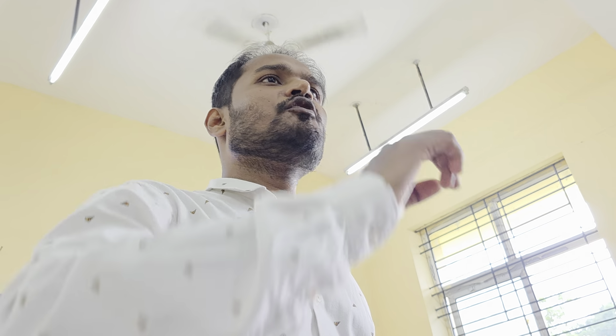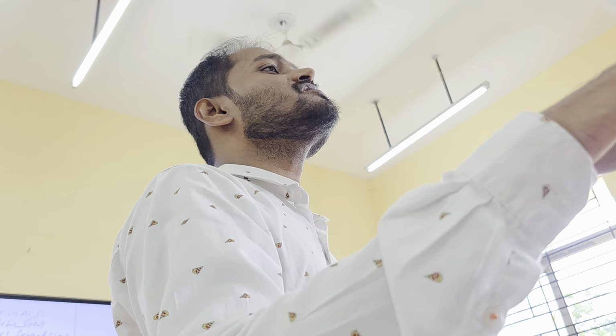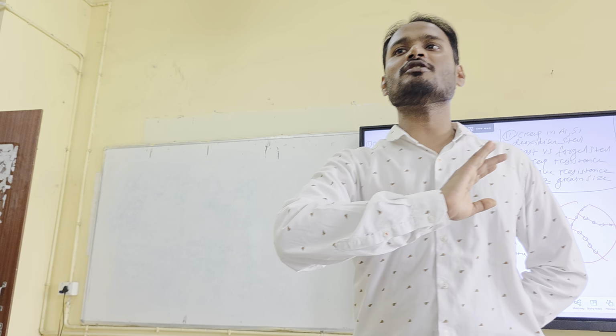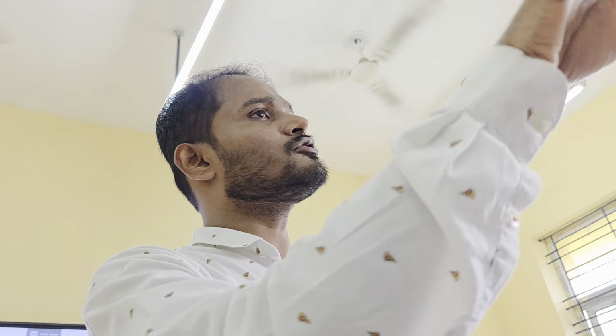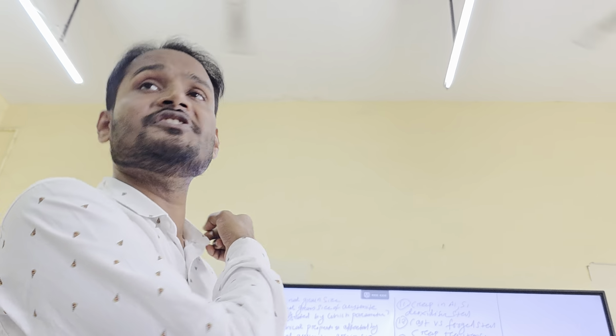But do you think it will happen for very high temperature? No. If you go to a very high temperature, 1200 degrees centigrade, what will happen? These precipitates will get dissolved in the matrix of austenite. So once they dissolve, nothing is there to pin the boundaries. So coarsening will start. So it doesn't mean that you can stop the grain growth at very high temperature, around 1200 degrees centigrade. It's not possible. But around 1050 is fine. Now I think you understood this one. Then there is another concept, see, deoxidation. I have written how deoxidation helps in hot working and heat treatment at high temperature.